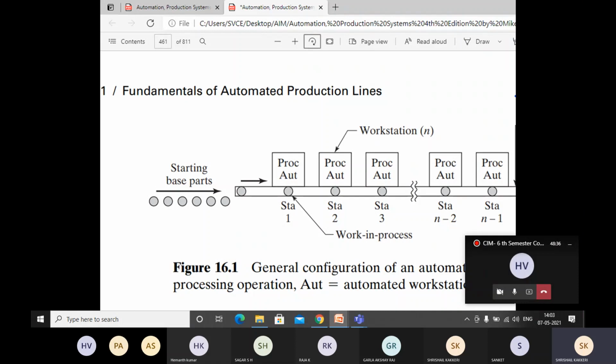It is also automated. So all these together, the transfer line, automating the workstations, automating the work holding devices, the part holding devices, and the robot, all this will be configured for a particular product only. So, hence the name indicates it is called a fixed automation. In this, due to all these, what happens? The initial cost, the high investment will be there. The cost of the system, the automated line will be more. In the beginning, it is a one time asset, but later on the labor cost will be reduced. Definitely the cost of the labor will be reduced.